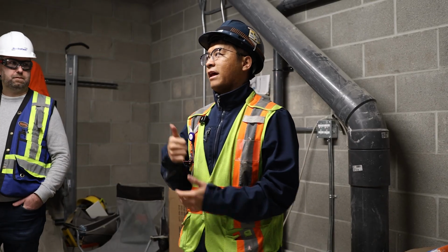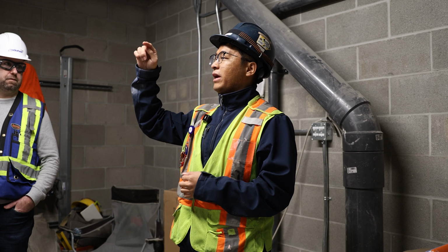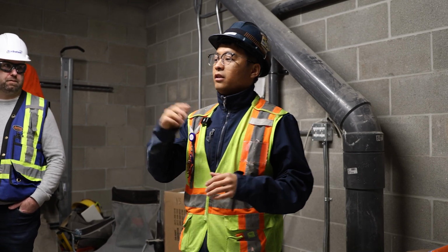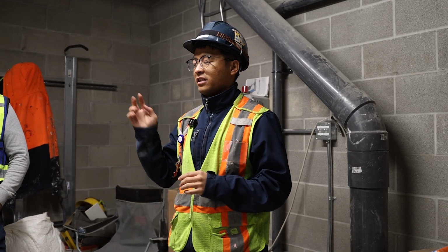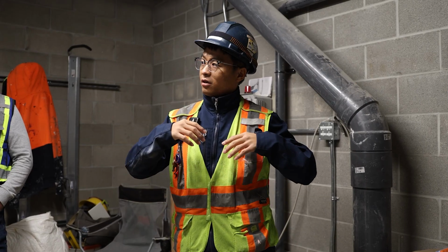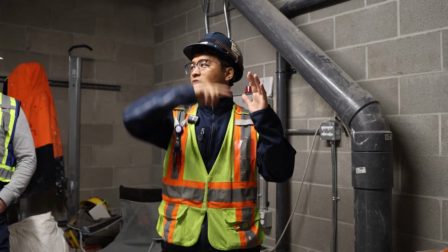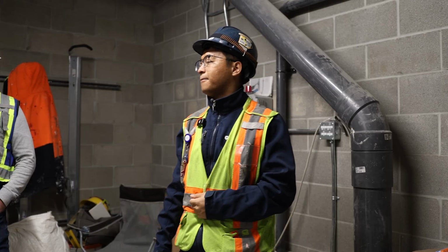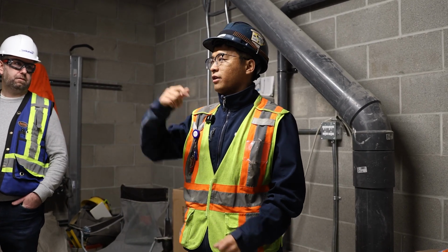Yeah. And the other thing I would like to be specific about is this MUA has a bypass damper. So what happens is the fan speed is a fixed speed. It's not on a VFD. The speed is not modulating. It's just a fixed speed. Whenever the space pressure goes too high, the bypass damper will open. The discharge damper will close. So it's just doing the recirculation inside the unit. Yes, on the BMS, you will see the damper position for the bypass damper.